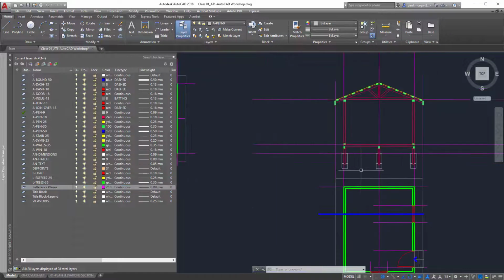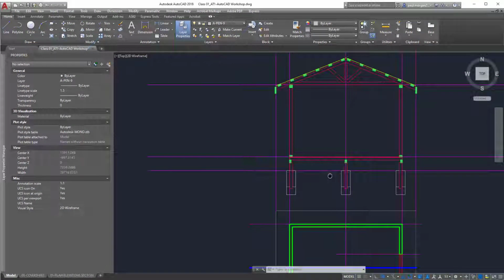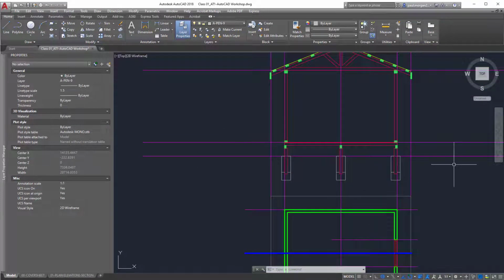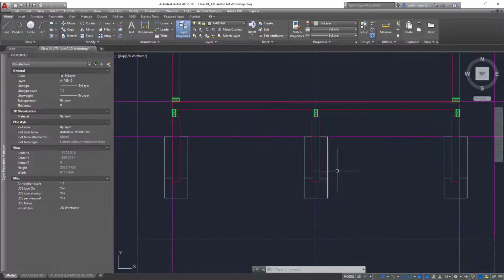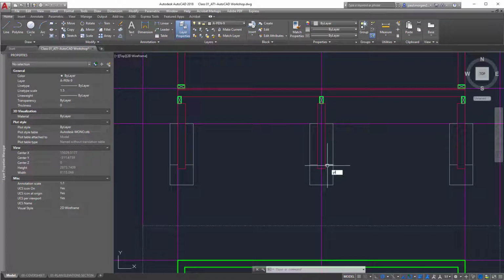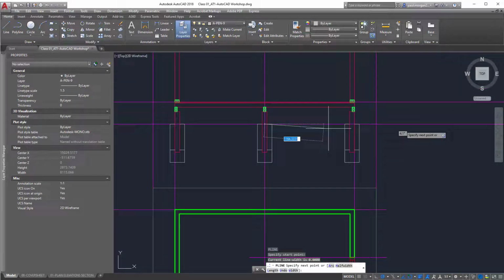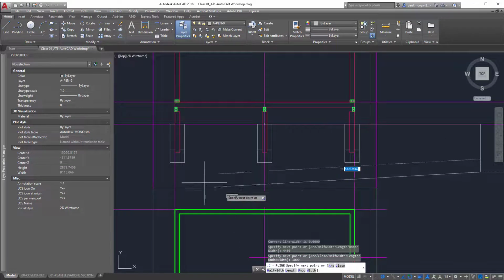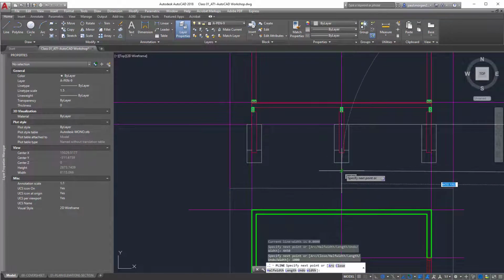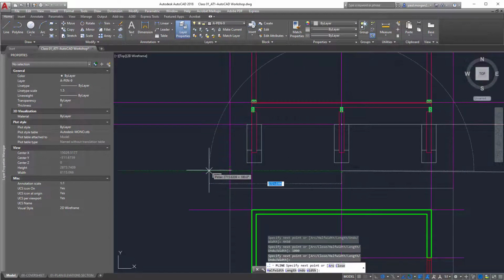All right. So next up is hatching. Down here, the earth fill and the hatching. So what I'll do is I'm going to take a polyline, and I need to draw the extents of the earth. So I'll start from the center, and I'll come out this way, and I'll go 4450. Enter. I'll then come down 1 meter, back to the center, and then I'll click again.